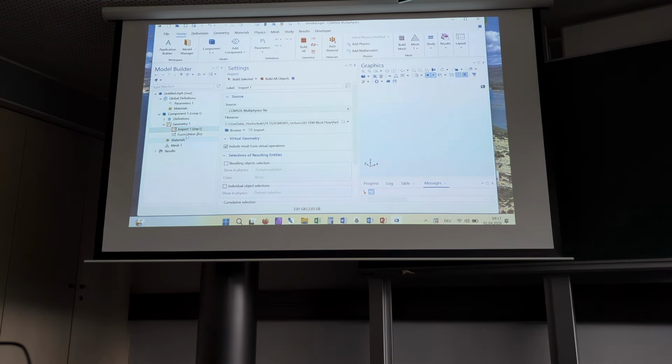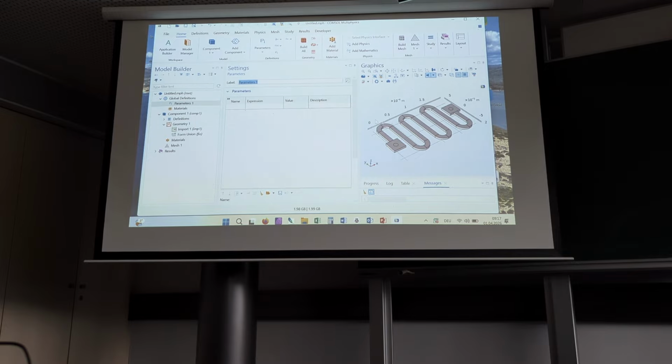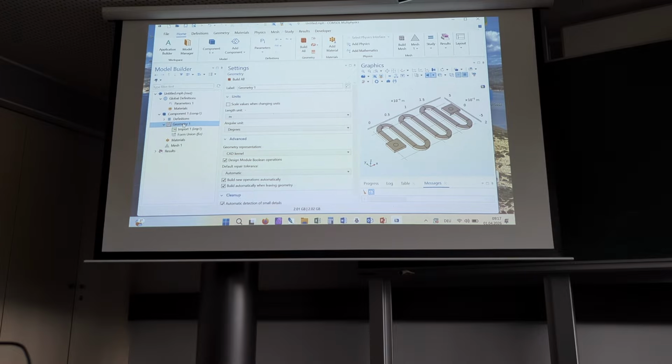You see we don't have a sequence in that case, so we cannot change anything, but hopefully if I hit build selected, we should have the finite geometry in here. I mean, we cannot change, it's not true. I can now start cutting off something, add something, that I can do, but on that structure itself, I cannot change, for example, a parameter. There is not even a parameter. If you may remember, for our thermal actuator, by inserting a sequence, we automatically got parameters. There is no parameter here, that means it's not a parameterized geometry. Anyway, it's a simple way to have the geometry available.